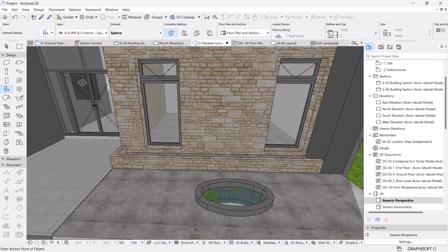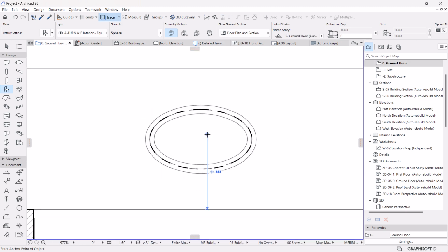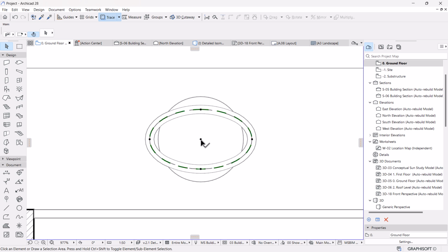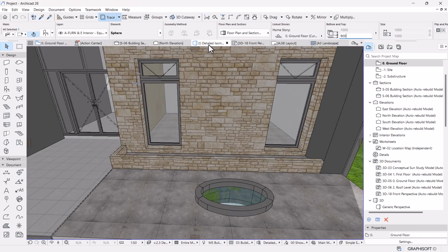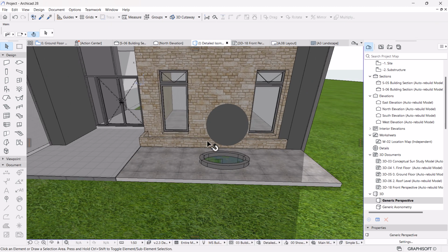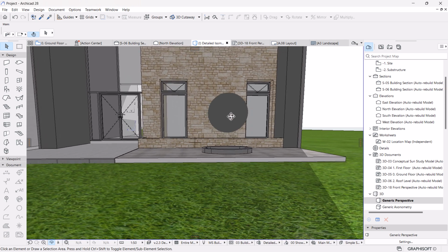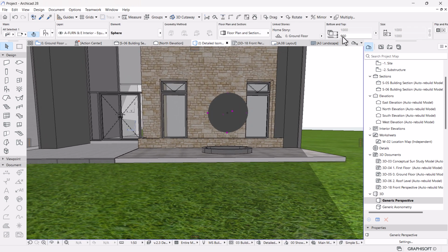and then hit OK. Let's go to the ground and place it right on the center of this, and set the height. Set the offset height for this from the floor to be, let's say, 900. If you check in 3D, we'll have something like that. Maybe a meter, 1.5.